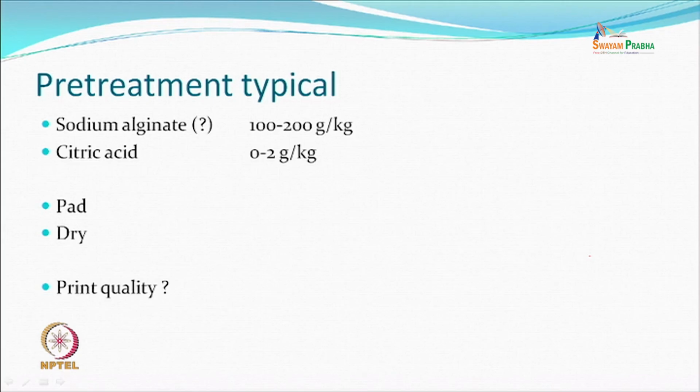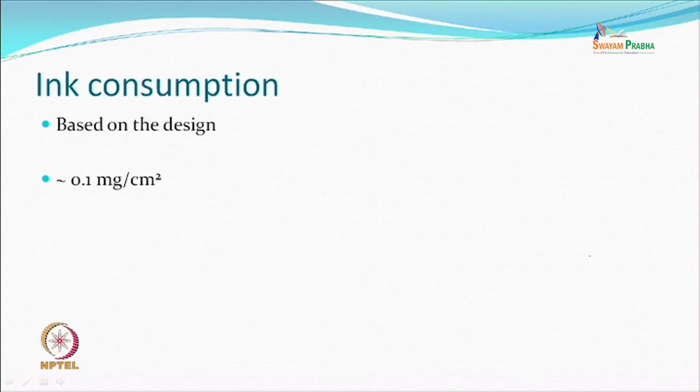So after this you pad dry, and then we hope for the best that print quality is going to be taken care of. The ink that is consumed obviously depends on the design, whether you are covering 100% or 30%, 40%, but generally consumption is not very high. We hope it is something close to 0.1 milligram per centimeter square, which is reasonable. Therefore the costing is based on this.